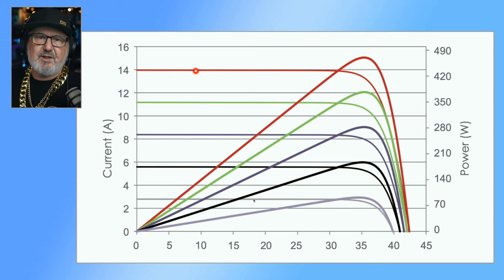But if you multiply voltage and current together, so at 14 amps and 0 volts, you've got 0 power. So therefore, this red line is the power curve of that 14 amp, starting at 14 amps IMP or ISC. And you'll notice the power is peaking, and that's the point that you'll get standard test conditions reading. So it'll say 475 watts, but it's only at this point here. So at this point here, if you drop straight down, you'll find that your current now is not 14 amps, it's a bit less. And also your voltage is not sort of 40 something, it's really down here somewhere around the 35 mark. So the shape of this curve really tells you the operating line of the module.